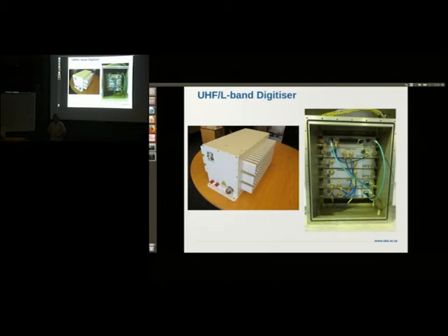So data rates, it's 10 bits times 2 polarizations, and we sample at 1,712 megasamples per second. So that produces 34.240 gigabits per second per antenna. So that's the digitizers. For the electronics group, the digitizer unit is fitted with a Kintex 7 FPGA.